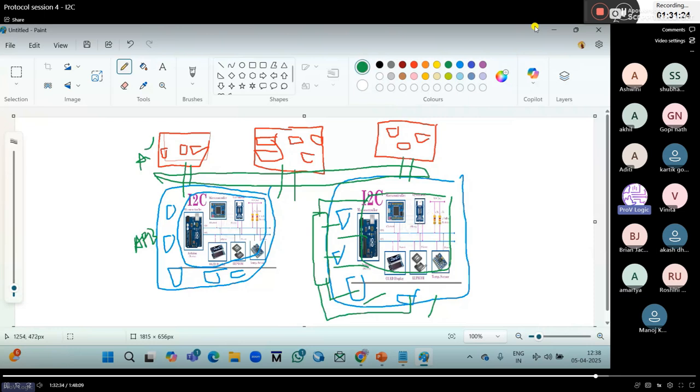Now this EPROM is there. EPROM is a slave. From this master to the EPROM, the data is communicated serially. If the EPROM is connected to some other IP here, then from this IP master to here through the bus, it will access parallel data only, right? Again, within the IP, this microcontroller sends the data internally as serial communication. But whatever transfer is there IP to IP, it will be accessed in parallel only. So now this slave needs to convert the serial data to parallel, right?